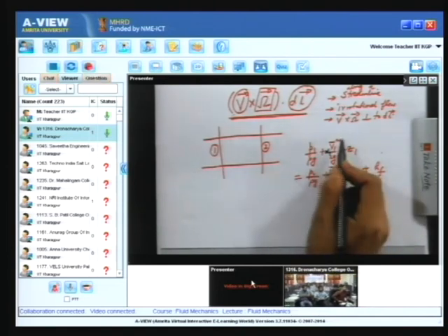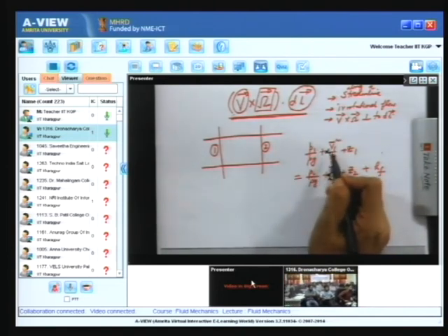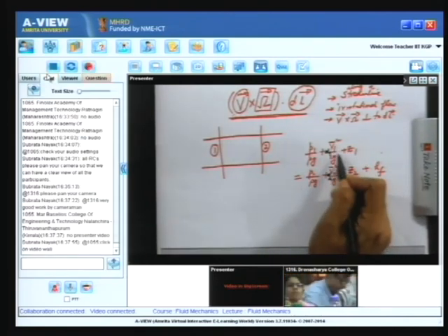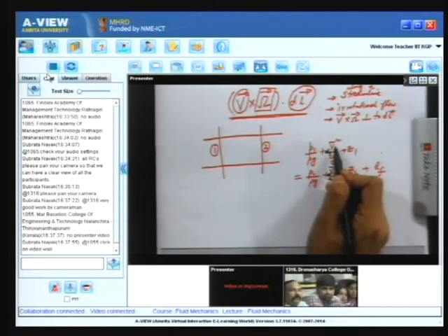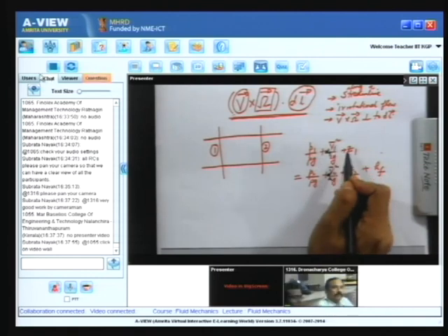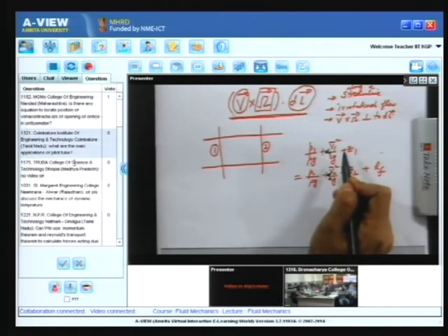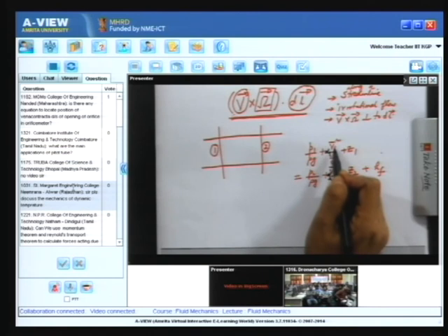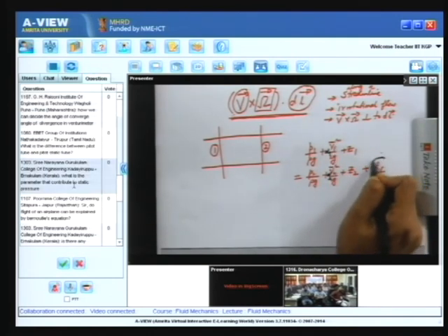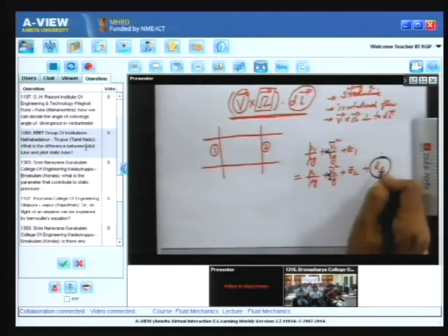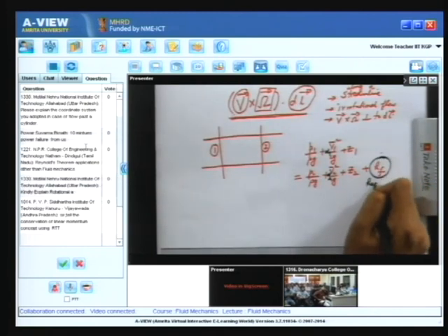These correction factors are there so that even with the average velocity of the sections we are able to represent the kinetic energy. So the first point is that we are not applying the Bernoulli's equation between points 1 and 2, rather we are writing the energy conservation between sections 1 and 2. To write the energy conservation we have a term HF which is positive, which is called head loss.